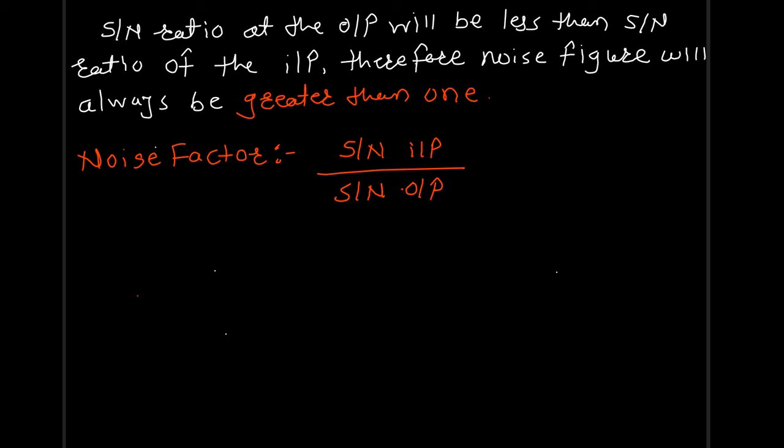The noise factor is rarely seen in specifications. The next one is the noise figure. Noise figure is the parameter that is seen widely in specifications and is in use when defining radio receivers and the elements within the receiver system. The noise figure uses a logarithmic scale and is simply the noise factor expressed in decibels.